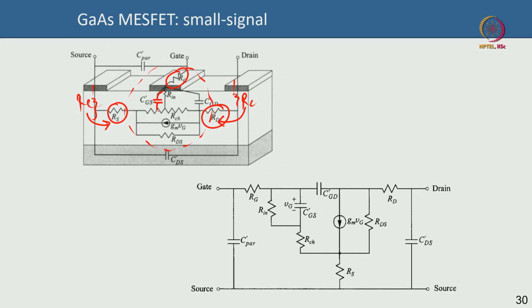Alright, this R in is basically your input resistance, it is basically the resistance to the gate. So if you have a barrier layer or an oxide layer or something, that is resistance to that. In general you have a certain barrier layer, for instance your capacitance is across the barrier, your resistance is also across the barrier, that is why this input resistance and this capacitance are kept in parallel. However, in certain textbooks I have seen that people also use this resistance in series with your CGS, the gate source capacitance, okay. But more or less the models work out similar, I think, at the end.